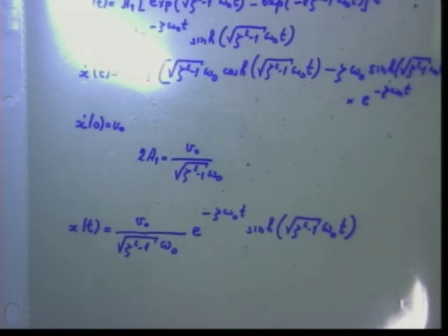Yes, Mr. Dale? The exponential function, even though it includes the natural frequency, if your zeta is still c divided by 2m omega sub 0, then you can remove that from the exponential. So your decay from the exponential is actually independent of the natural frequency. Yes, that is correct. If I substitute the values of zeta and omega sub 0, then omega sub 0 will disappear. Yes, that is correct.